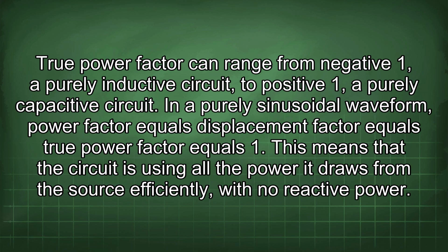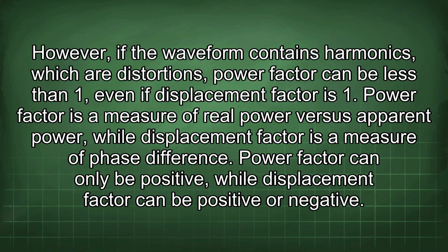In a purely sinusoidal waveform, power factor equals displacement factor equals true power factor equals 1. This means that the circuit is using all the power it draws from the source efficiently, with no reactive power. However, if the waveform contains harmonics, which are distortions, power factor can be less than 1, even if displacement factor